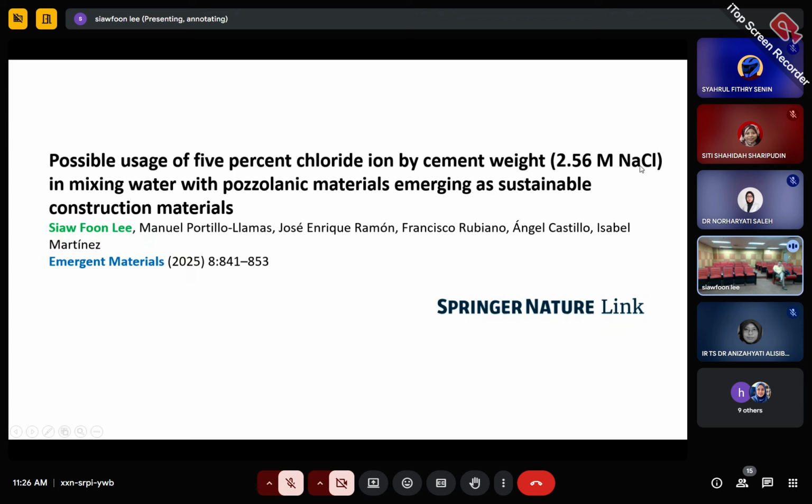But as known, the chloride ion is an aggressive ion. It will break down this passive film. So either we recycle the effluents to clean water, or maybe we think that we can reuse them inside the concrete, and see what is going to happen to the steel if we reuse this kind of solution with a very high concentration of sodium chloride.